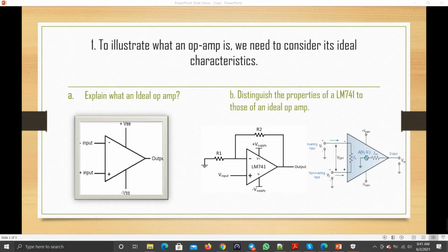100,000 if you operate an op-amp in open loop condition without negative feedback. Even a microvolt of input voltage will drive the output to saturation. Almost all amplifier circuits with an op-amp are configured to use negative feedback, which reduces the voltage gain. Otherwise, its output will always be at saturation, positive or negative.